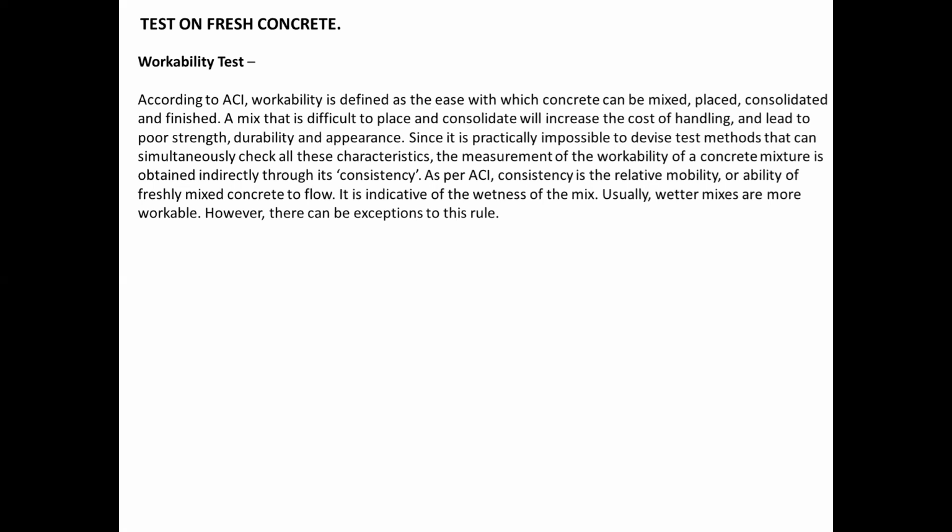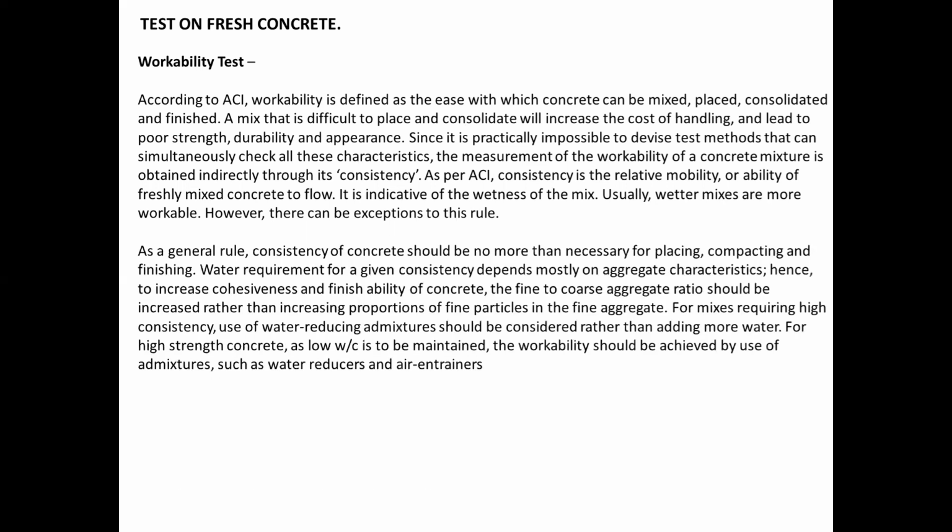As per ACI, consistency is the relative mobility or ability of freshly mixed concrete to flow. It is indicative of the wetness of the mix. Usually, wetter mixes are more workable. However, there can be exceptions to this rule. As a general rule, the consistency of concrete should be no more than necessary for placing, compacting, and finishing.